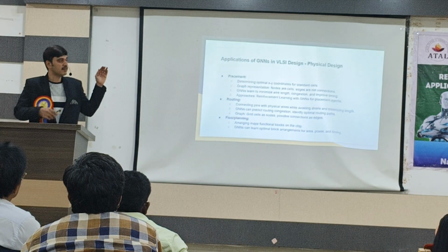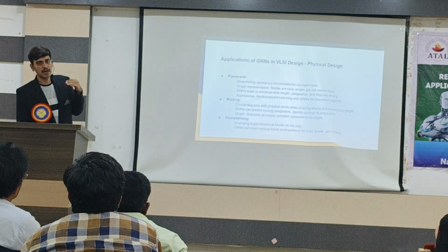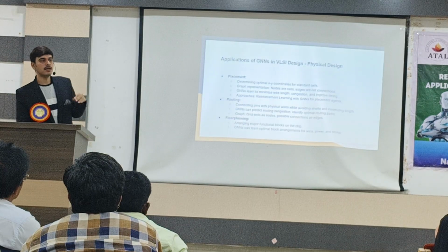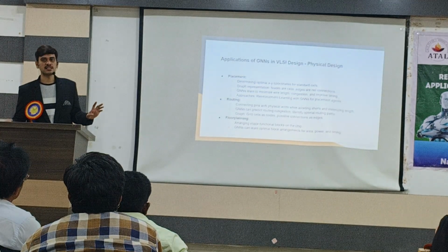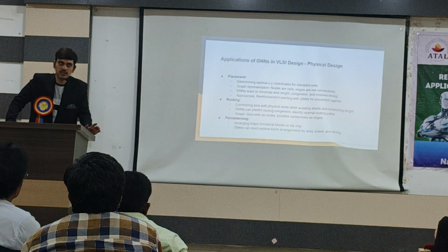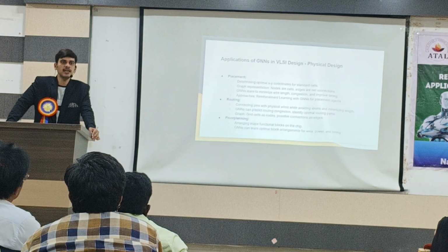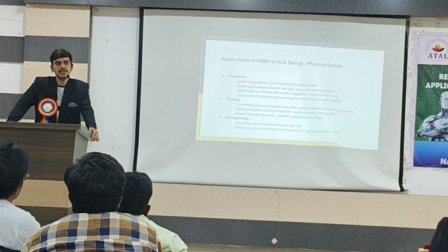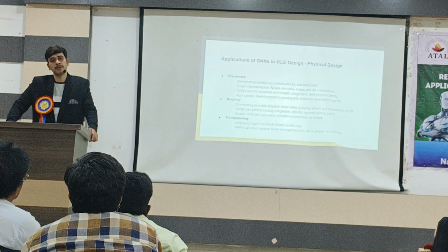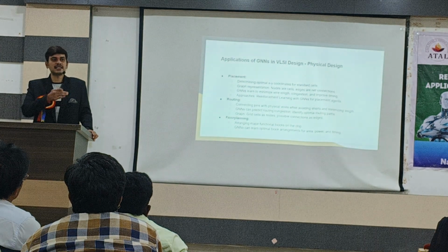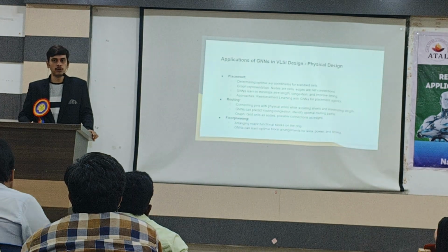And here you want to explain. Once we have the synthesis DB, we do the initial timing analysis on the synthesis. In synthesis, we don't have clock details actually. So that's why we won't check the hold. Because unless we propagate the clock, we can't get the hold, because clocks are not there, those are the exact requirements we don't know.